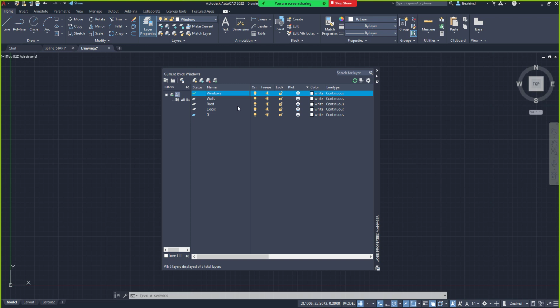So if there is a layer of my design that I don't want to show in my print, all I need to do is come to my plot and click on this print icon, and then you see an icon. Can you see the red icon that shows minus? Yeah. That layer won't come out of my print, of the drawing plot that I'm trying to bring out. That layer won't show. I'm telling AutoCAD not to plot this out for me. That's that about plot. We'll be talking more in detail about this.